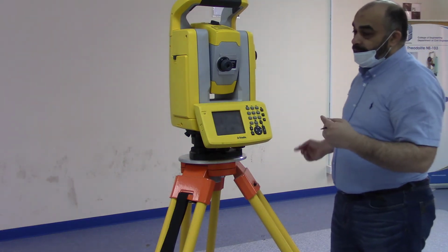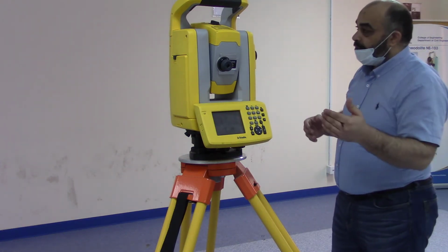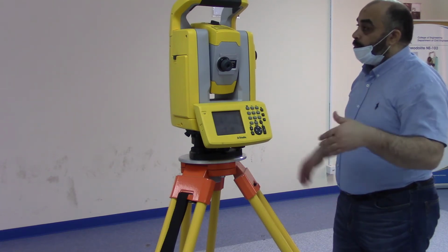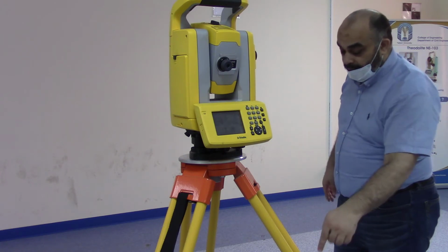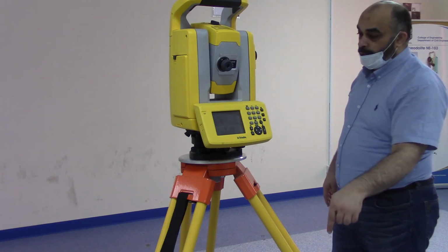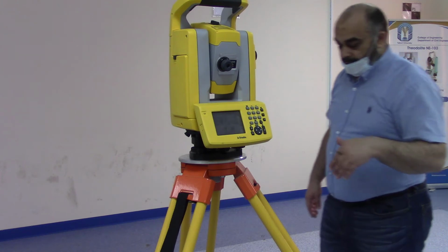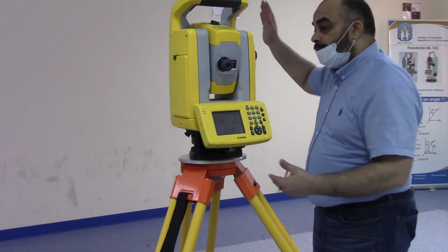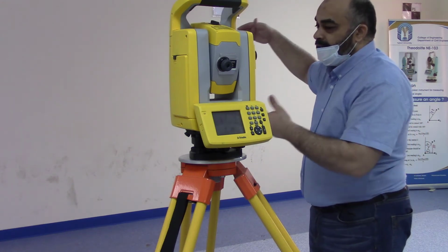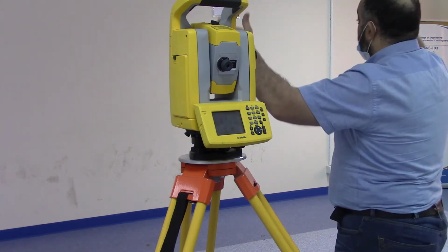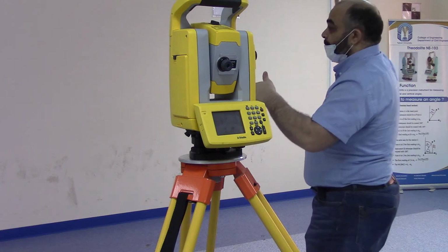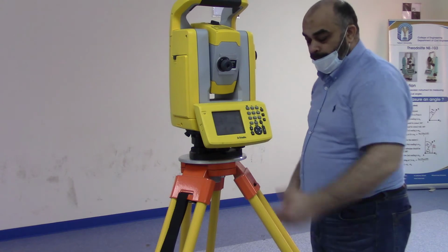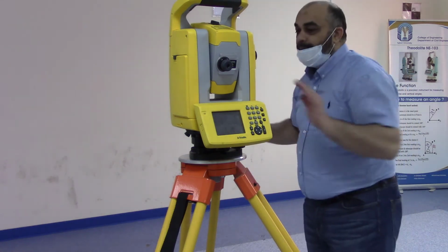After doing this, automatically using triangulation, the total station program will calculate the coordinates of this point, O2. In that case, the total station will calculate the coordinates of this point and set up your north, because you have Easting, Northing and Elevation according to what you have entered as values for P2 and P6. So it sets the north direction and the coordinates of point O2, and you start the measurement.